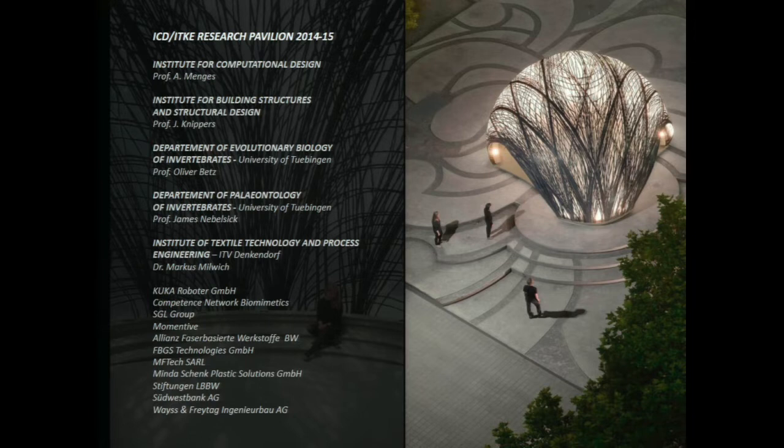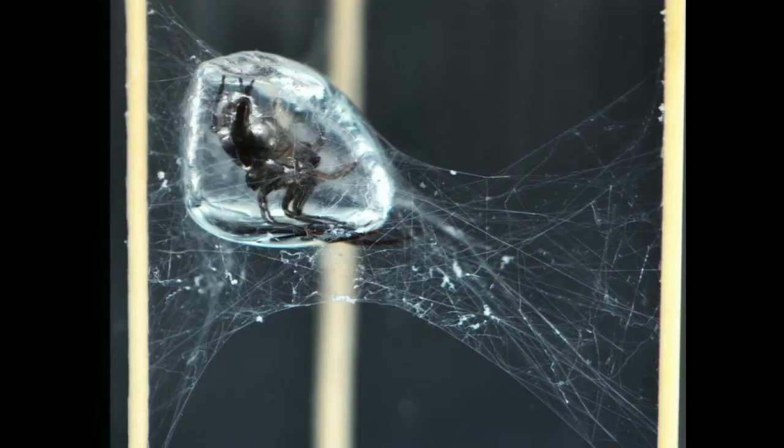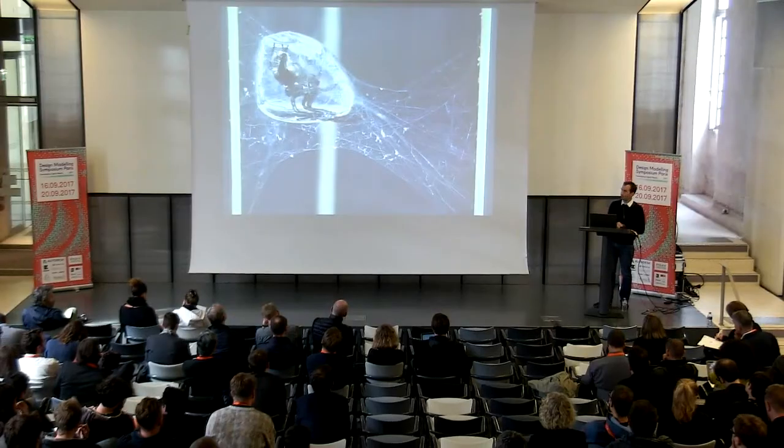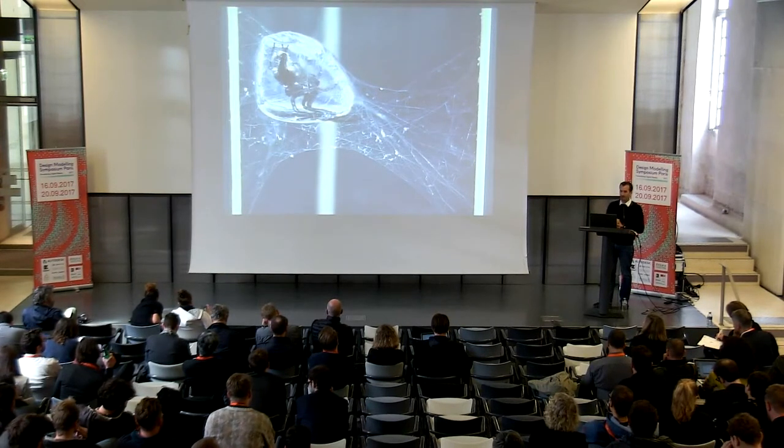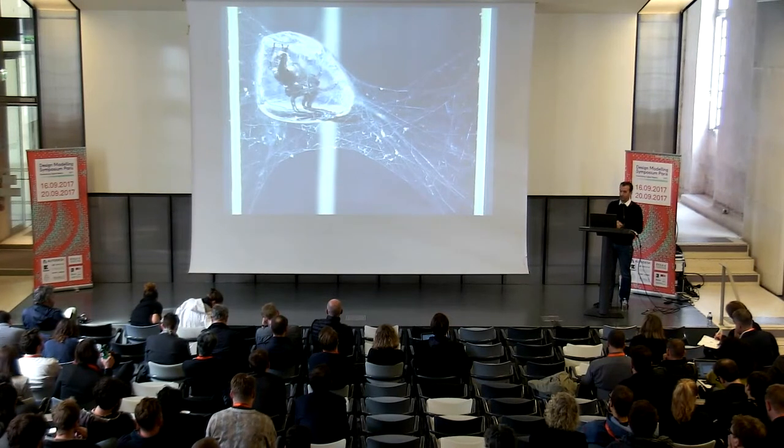exploration is something that can go quite a step further, and that's what we tried with this research pavilion, where we looked into the minimization of the formwork to an inflatable onto which we then lay the fibers, so that ultimately the inflatable becomes stabilized and becomes a compression shell. So there are good reasons, we were told, why nobody has embarked on using pneumatic formworks for carbon fibers, because you have a material that has hardly any elasticity, and then you have a formwork that most likely is going to deform in the construction process. So these two things don't go very well together. But then it's interesting to see that in nature, there are examples where this contradiction has been resolved.